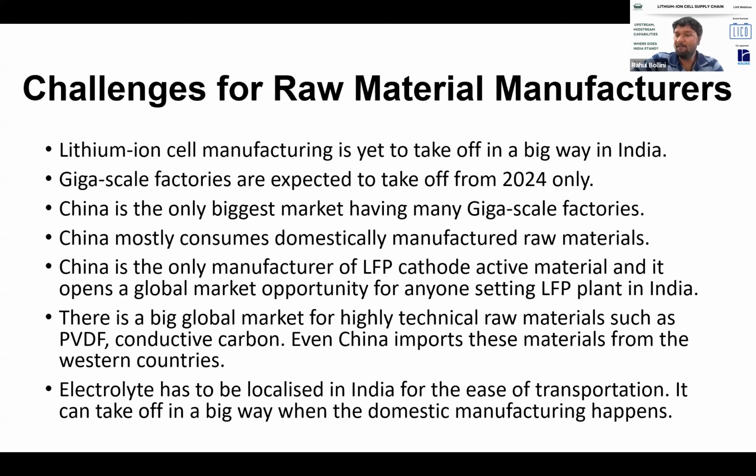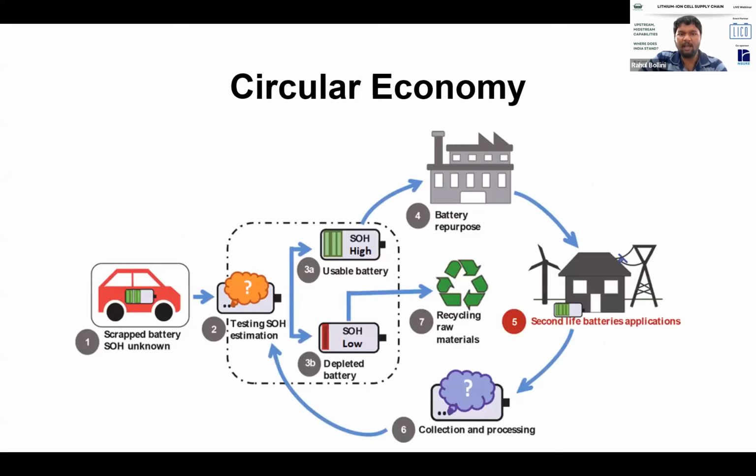And electrolyte is something which is always advised. Whenever people are working towards cell manufacturing, any technology partner advises that you try to procure your electrolyte locally, because it's highly sensitive to air and water and even sunlight. That's why the way it is packed, it looks very, very secure. Generally, initially people start by importing the LiPF6 salt and then adding the solvents and additives here. But eventually, I think even the salts can be made here if you go towards backward integration using hydroxide and all.